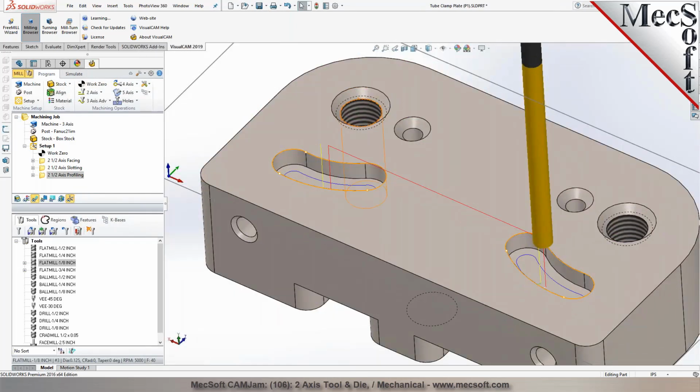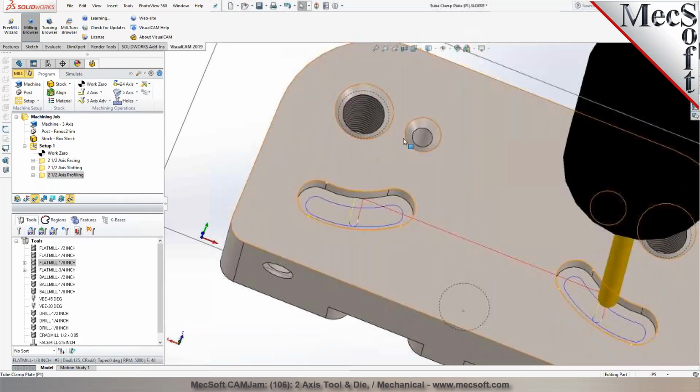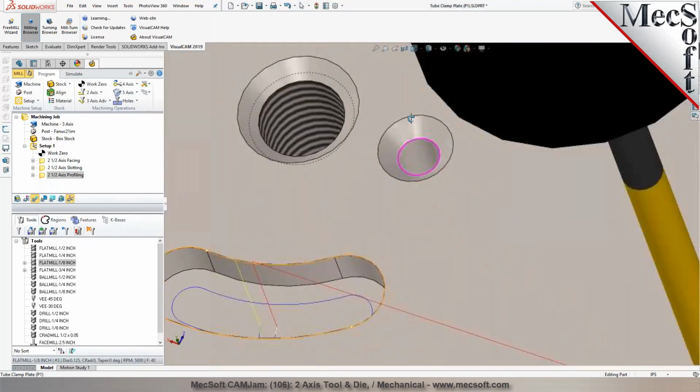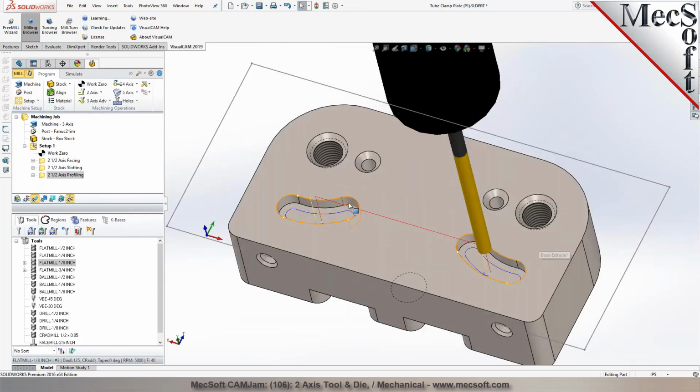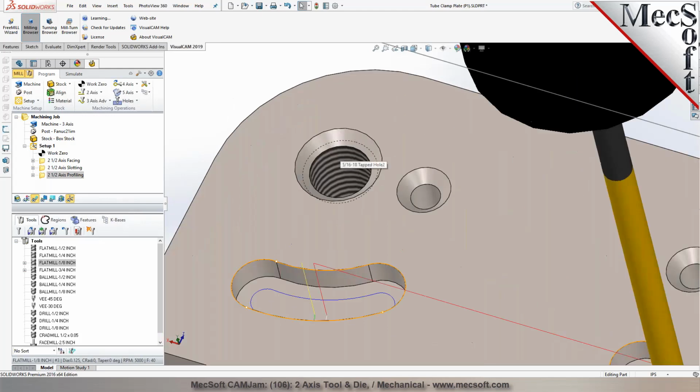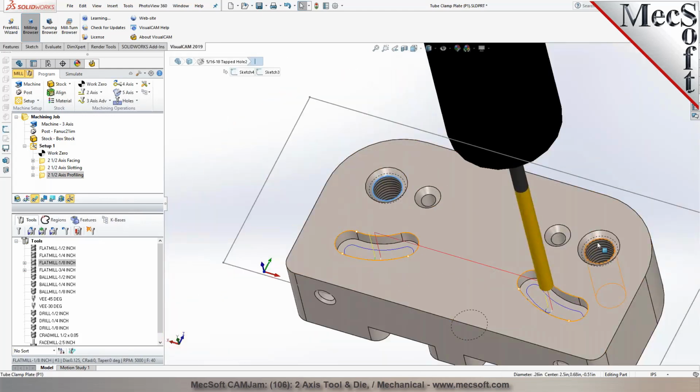So the next step, you want to do these holes in here, and then you want to go ahead and do the chamfers, right, or countersunk using different operations. And then do a profile cut around the periphery. You can do it from this side, or you can flip it over, machine it, and then cut the profiles as well. So here I can check the diameter of the holes. So this one is 0.26. Are these two the same size holes?